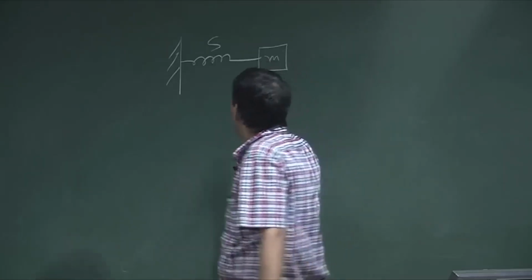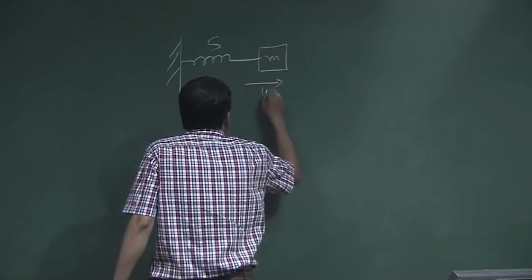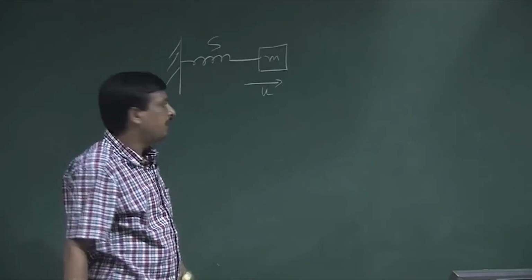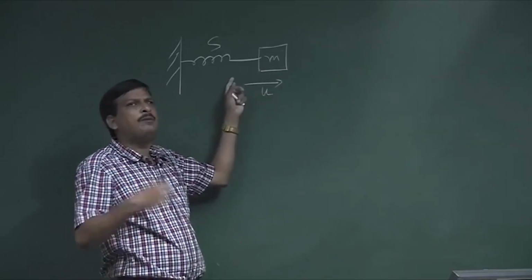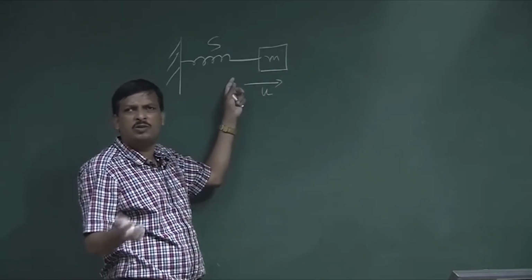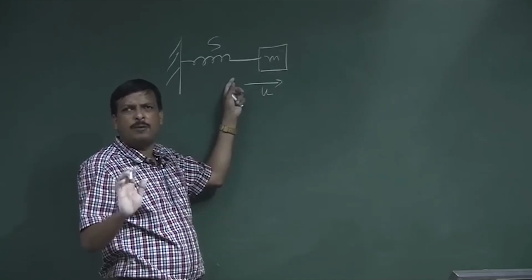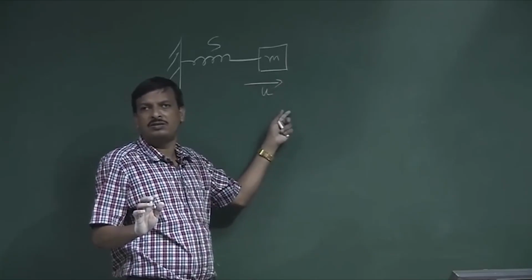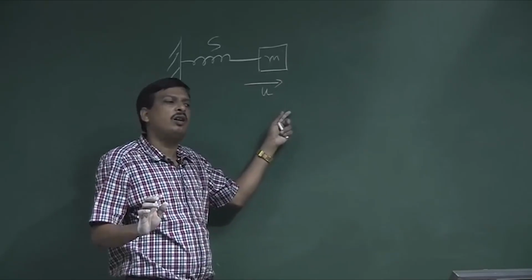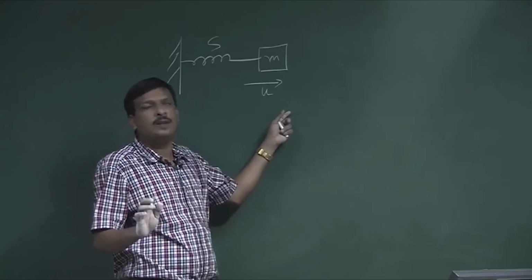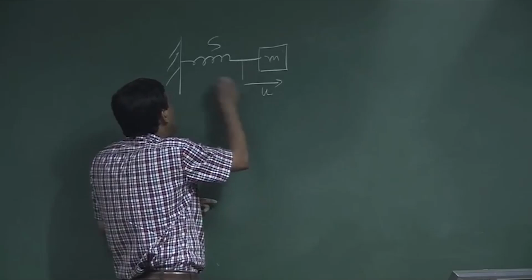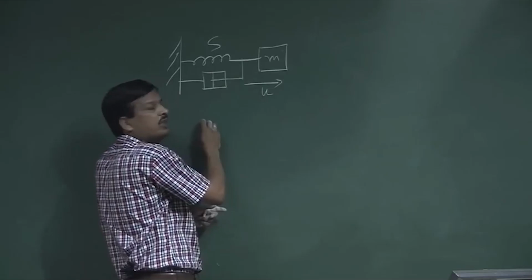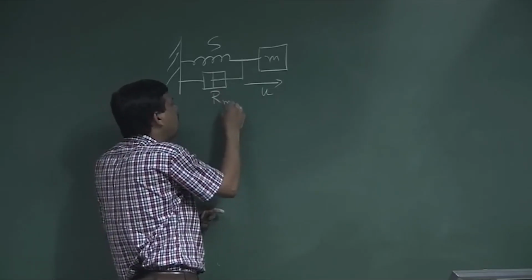So, that means if this mass is moving with a particular velocity u, then the applied force, it may be a friction force, it may be a viscous force from a liquid, whatever that applied force is, it opposes the motion of the mass. Okay. That is called damped oscillation. That means, as if I am applying a mechanical resistance to that oscillation, and mechanical resistance is called Rm.